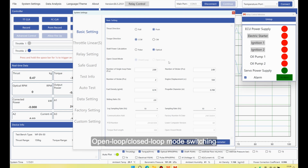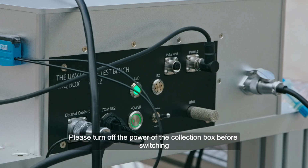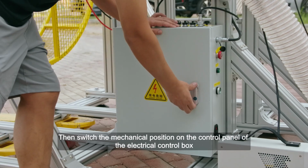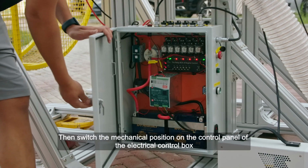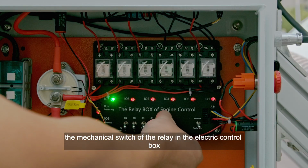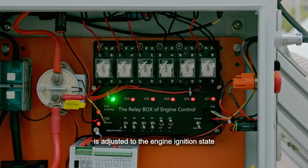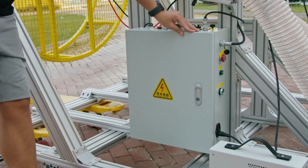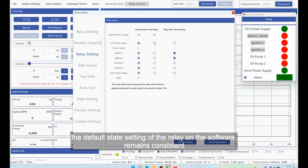Open loop or closed loop mode switching. Please turn off the power of the collection box before switching. Then, switch the mechanical position on the control panel of the electrical control box. In the open loop mode, the mechanical switch of the relay in the electric control box is adjusted to the engine ignition state. That is, the power supply of ECU number 1 and ignition 1 of number 3 are set to the closed state, on. At the same time, the default state setting of the relay on the software remains consistent.